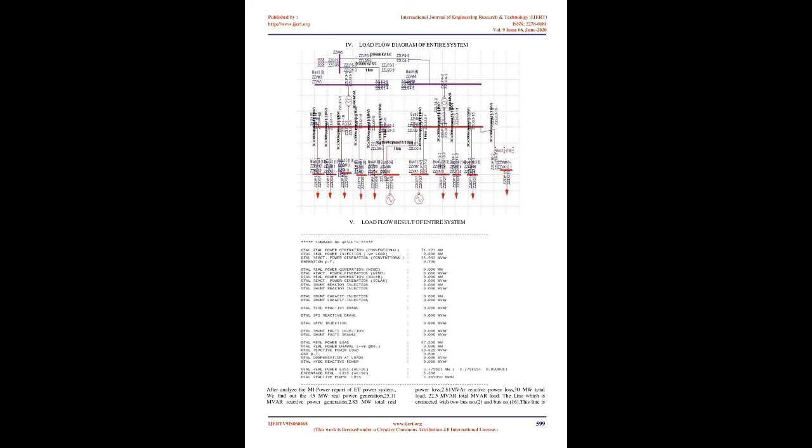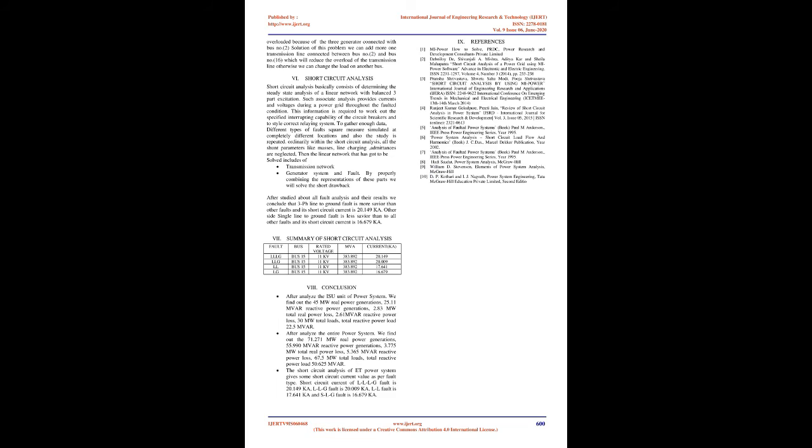The purpose of any load flow analysis is to calculate precise steady-state voltages and voltage angles of all buses within the network, for fixed load, generator real power and voltage conditions. Once this information is known, the real and reactive power flows into each line and transformer can be determined. Additionally, as generator reactive power output can be analytically determined, a power flow analysis for a system under actual or projected normal operation conditions, the base case, provides the results that represent a benchmark for comparison of changes in the network flows and voltages in abnormal conditions.